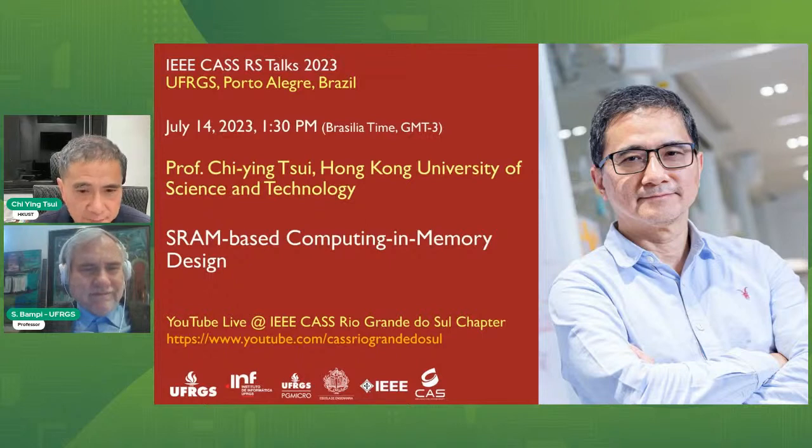Yeah, I think CIM is very promising. We have different groups in our center looking at different types of CIM design. We have a group working on digital SRAM-based CIM, and also a group working on RRAM-based CIM. We are looking at ways to accommodate the variations of the RRAM. Of course, RRAM can achieve very high energy efficiency, but the problem is accuracy. So how do we pick the right CIM to use? It all depends on the type of application we need to target. We have different trade-offs in terms of accuracy, throughput, and energy efficiency, and there is still a lot of work we can do on these issues.